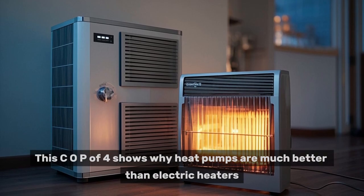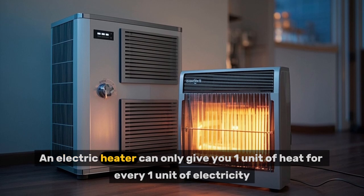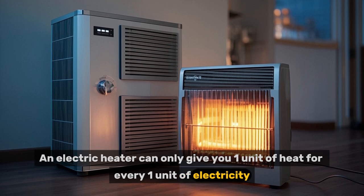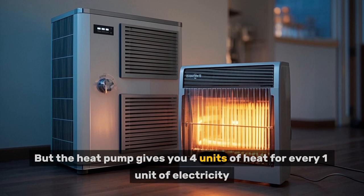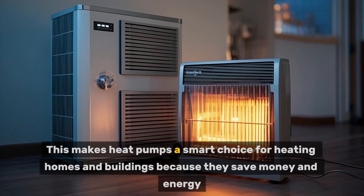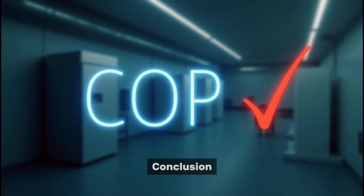This COP of 4 shows why heat pumps are much better than electric heaters. An electric heater can only give you 1 unit of heat for every 1 unit of electricity. But the heat pump gives you 4 units of heat for every 1 unit of electricity. This makes heat pumps a smart choice for heating homes and buildings because they save money and energy.